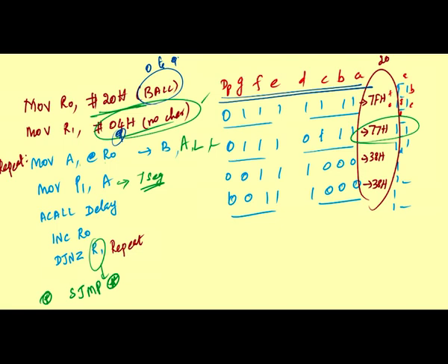Now, you read it. For A, all of A, B, C, D, E, F, G except D are on. So I apply the value 0 to D, and the remaining are 1. Then you read it. Now, for L, A, B, C, these 3 bit positions are off, then D is on. A, B, C, D, E, F, G, right. Now, you write the corresponding bit positions: E, F are on, then G is off, and this one is also off. The same thing for the other L also.